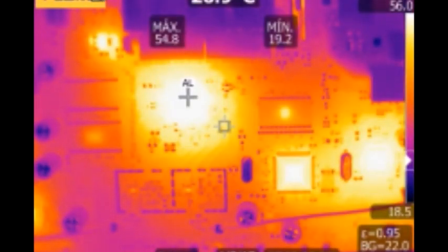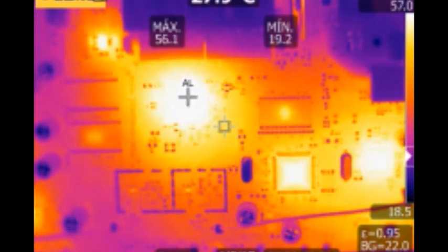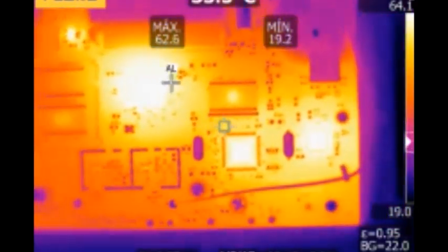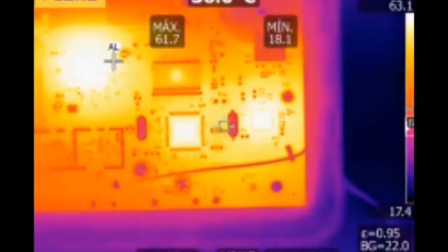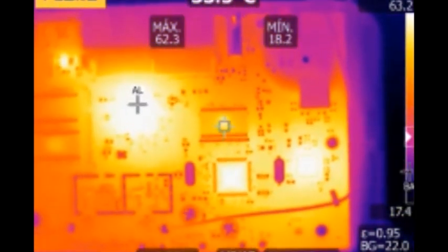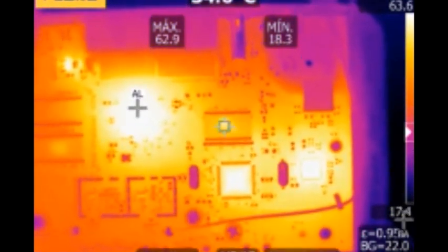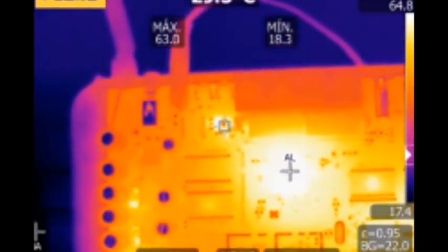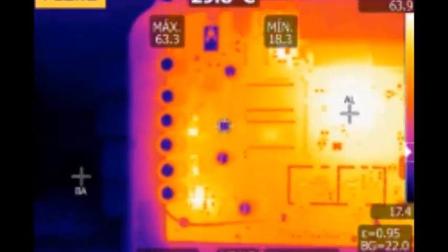In this video, we can see how an electronic board heats up when it is fed and how the temperature of each electronic component is increasing till the steady condition. So, after reaching a stable temperature, we can analyze each of the integrated circuits of the electronic board. As electronic components can be very small, we need to consider what are the key parameters of an infrared camera so that we could detect problems properly.